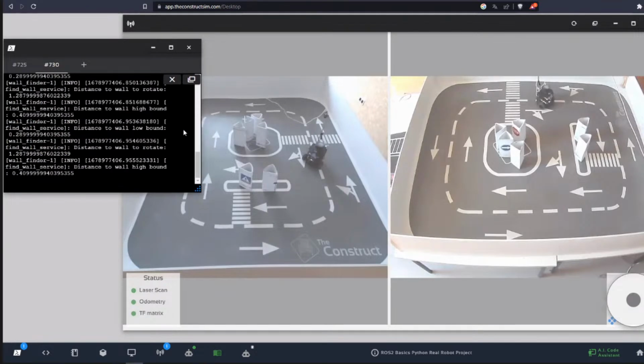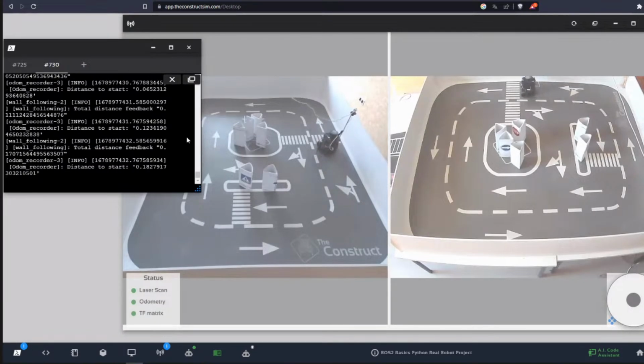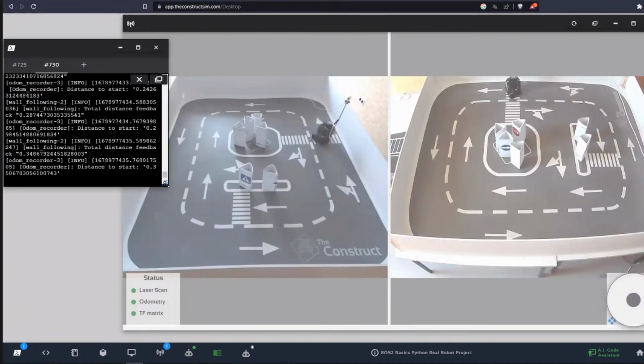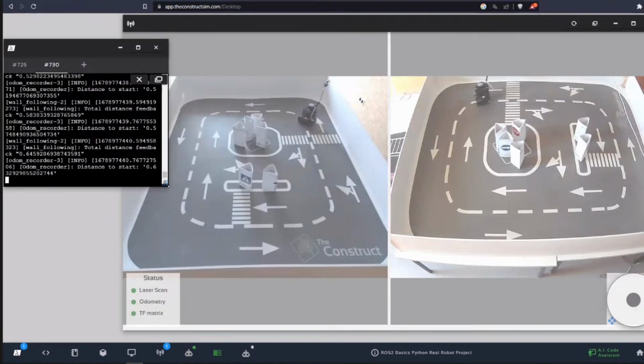The robot will find the shortest laser reading and take its index, and according to that index it will turn left or right because of the efficiency. After it comes closer to the wall, I think it was 30 centimeters, it turns its right side to it, and after it turns, the odometry value takes that position and saves it because it needs to check if the lap is completed or not.